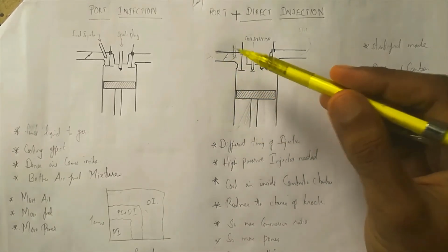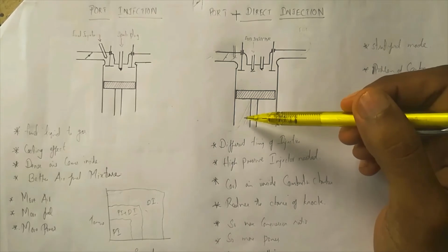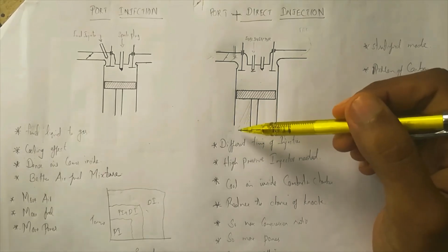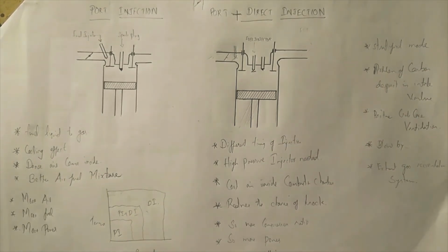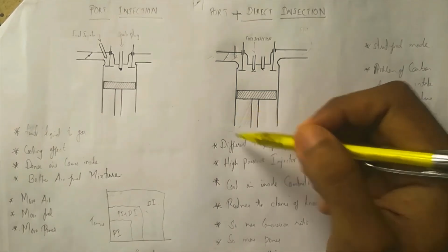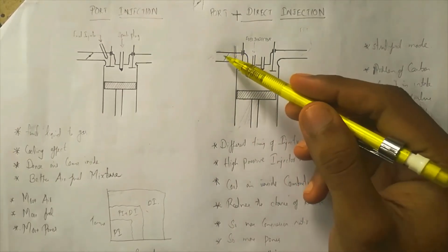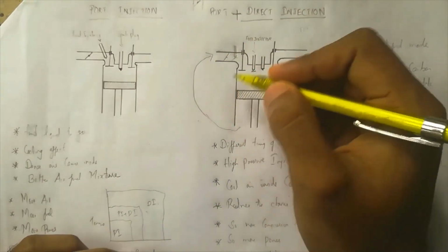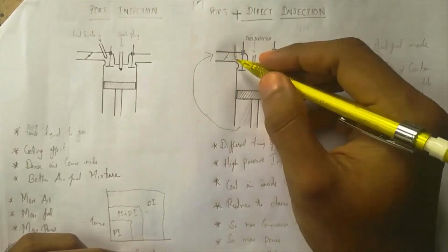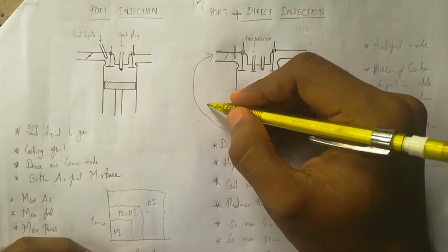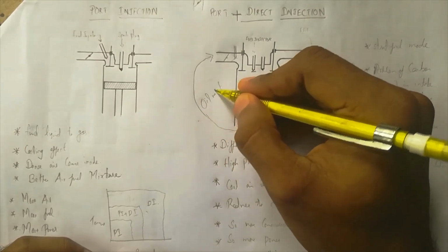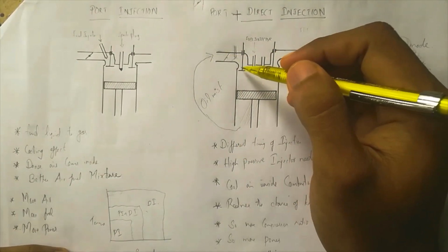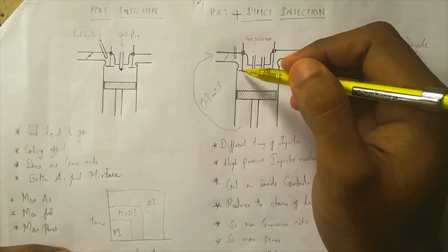So here we have to pass this air, because it will pressurize the crankcase, right? So we have to keep a breather, or we should have a positive crankcase ventilation here. That means whatever air comes into the crankcase will be fed back to the intake port. So we have a mechanism for that. And the gas which is going back to the intake port actually contains oil mist and some burned gases, and when it hits these intake valves, it sticks on top of them and makes them dirty.